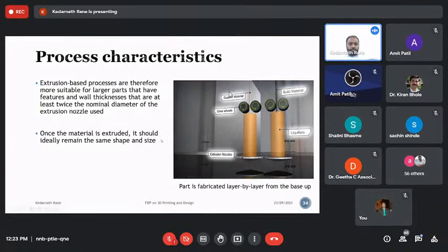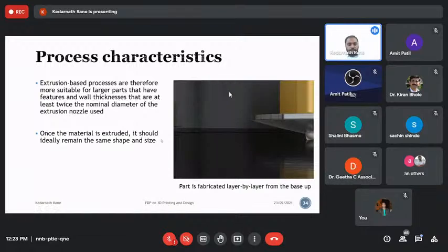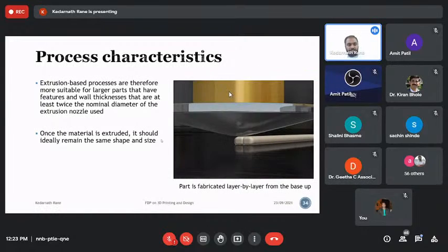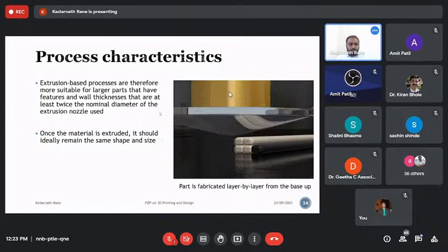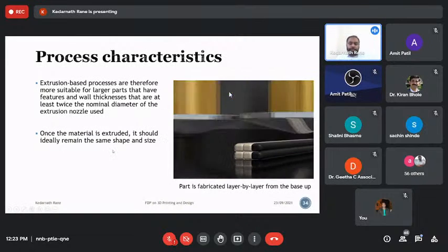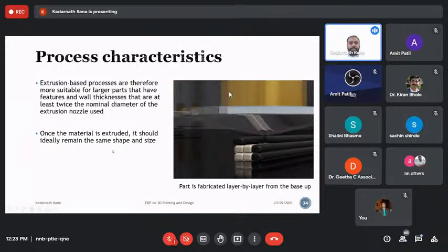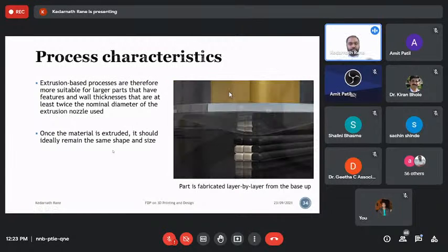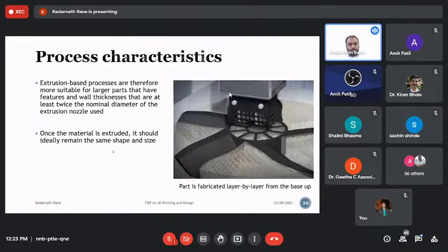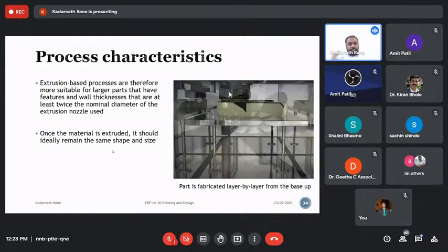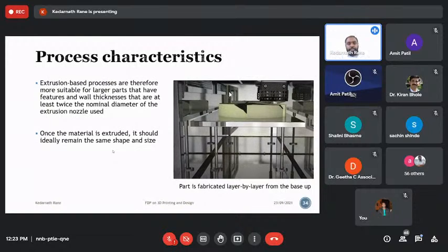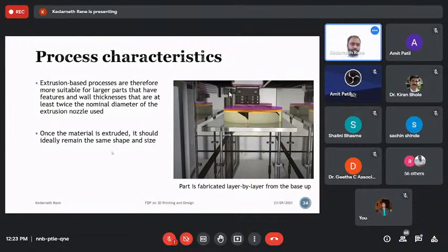The strands already deposited beneath the new surface should not distort. That is a requirement. So that's why sometimes cooling fans are introduced in the chamber itself, so they can cool from the bottom and heat from the top, to maintain the stability of the part as required.